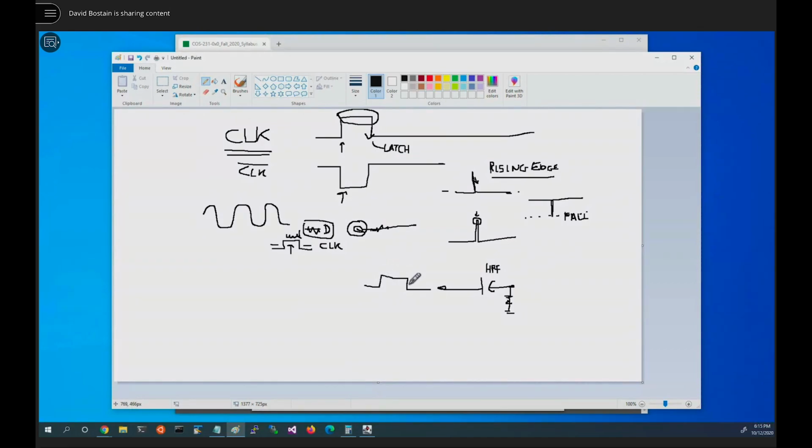So what we're basically trying to do with this circuit that we build here is we're trying to grab only the high frequency stuff, because most of them are based on these two lines right here. Most of this other stuff has to do with the main frequency of the signal. But if we could grab these high frequency signals that are making up these two edges here, then we'd be able to present them as output signal. And that's exactly what this high-pass filter configuration does.